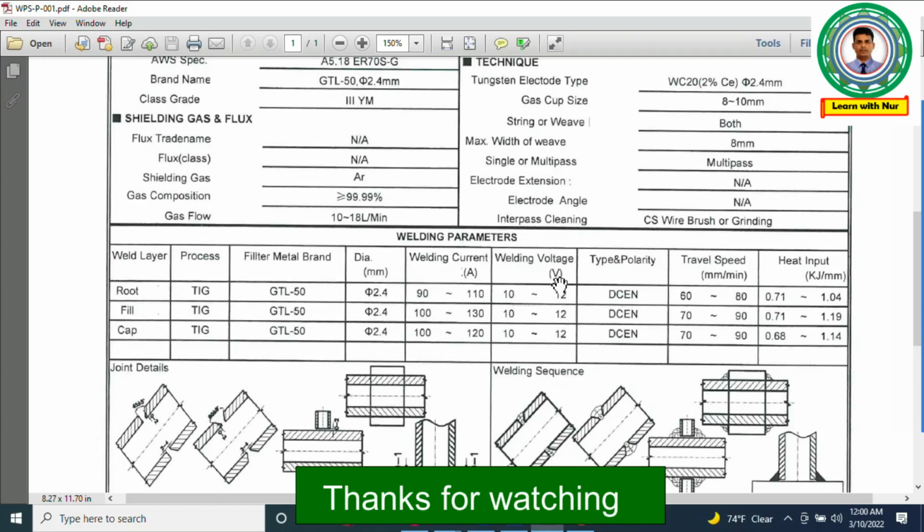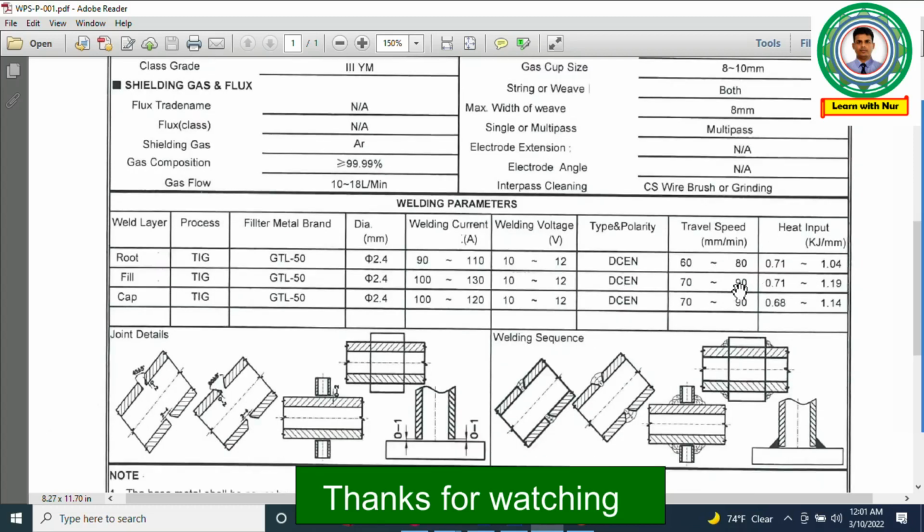Same as welding voltage, we have to follow within 10 to 12. Then type of polarity will be DC negative. Then travel speed, minimum minute per mm, 60 to 80, 70 to 90. So we have to follow these things. Then heat input will be this much. So during welding we have to keep the welding parameter record. What current they are using, voltage, and what the travel speed is.